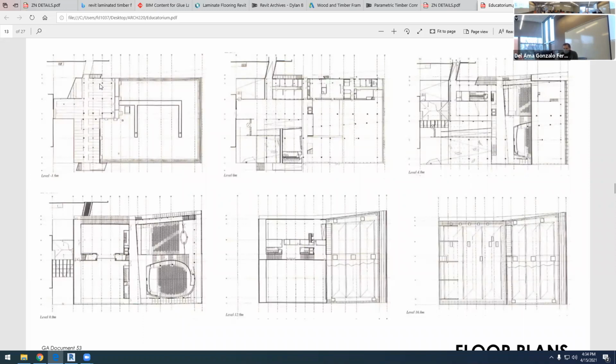And the parking lots, yes, because if you need to place 2 cars between 2 columns or 3 cars between 2 columns, that will give you the distance between columns, and that's it. So it depends on the size of the car, basically. Is this a parking lot? I'm not sure. I don't think so, but it looks like it. But if we had a parking lot underneath this building in the underground, then the structure would reflect the parking lot. And this is something that we need to be aware of when you're designing buildings.